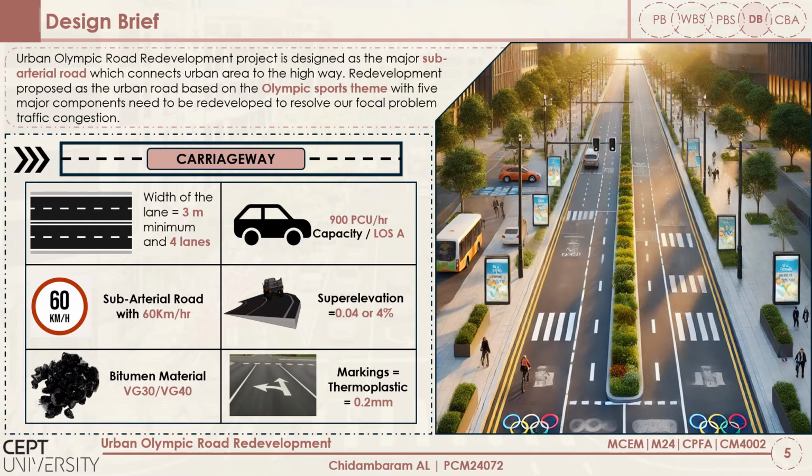The next assignment is design brief. Strategic design brief is given by the client to design consultant with unique specifications which should be followed during the design phase. There are five major components to be redeveloped in this project. One is carriageway, then footpath, central median, junction improvements, and on-street parking.